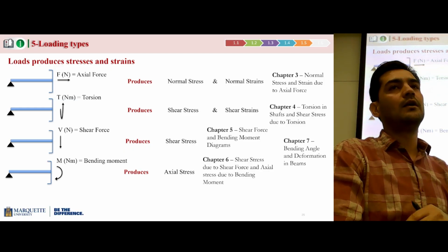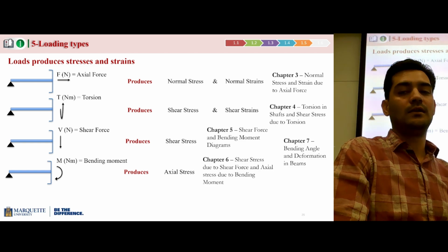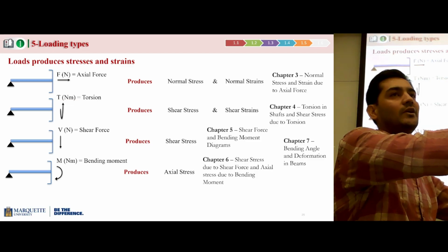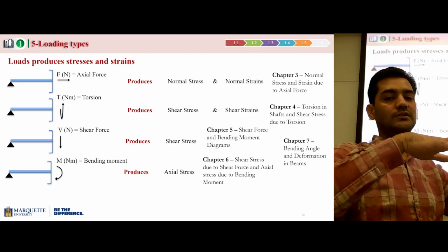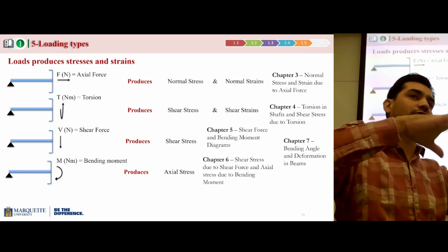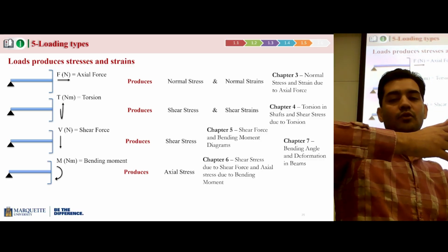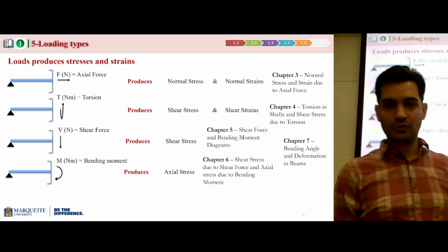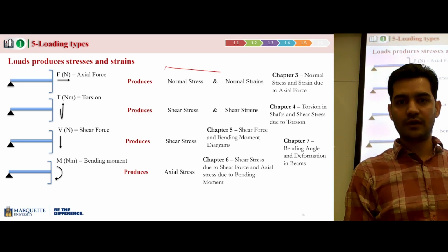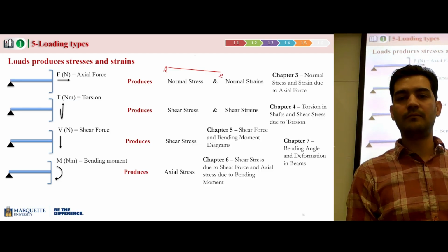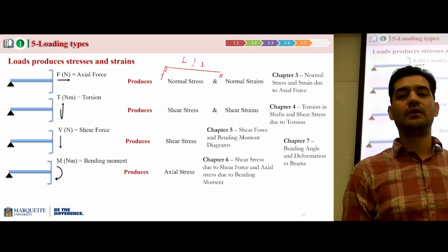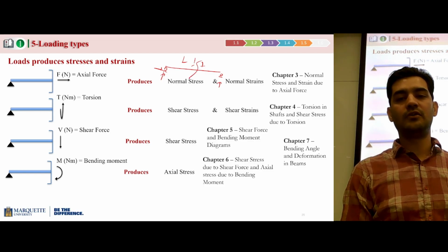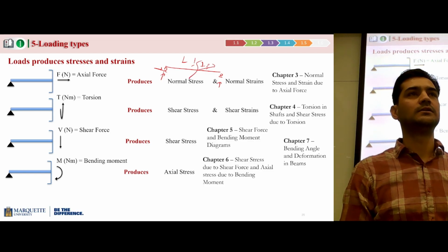So far we'll talk about the stresses, but as we know now, we are beyond the rigid body assumption. So the forces will not just create stresses, they will also change the shape. Changing shape means it will cause deformation, it will cause bending. I don't know if you have done this in statics, but if you have a simply supported beam with a bunch of loads, you calculate the reactions to those loads, and you'll also have internal forces.